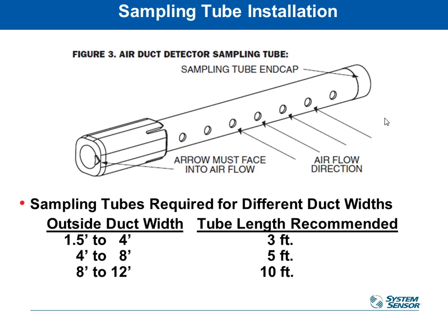Generally, you need to have that tube go across the full length of the duct. I think technically by code it only has to go 80% of the way. However, if you have it going 80% of the way, that means there's nothing really supporting it on the other end. So most people just go all the way across. So for example, if you have a 2-foot wide duct, you would put in a 3-foot tube and you would cut off 1 foot of that tube so it's only 2 feet long. You don't have it sticking out the end of the duct on the other side. However, let's say I had a 12-foot duct, I would put in a 10-foot tube because it's the largest one that's available, and that does make it 80% of the way across, then I'm fine.